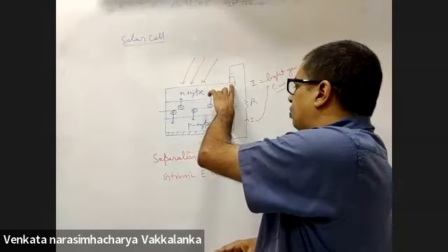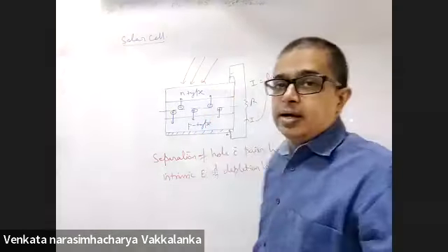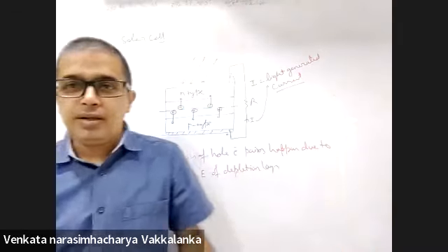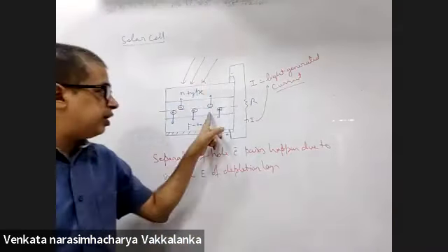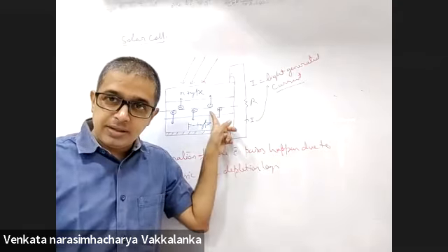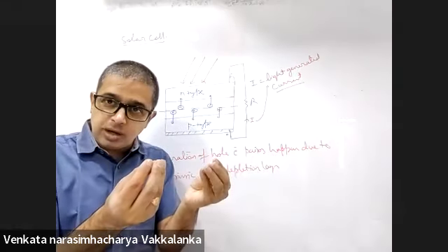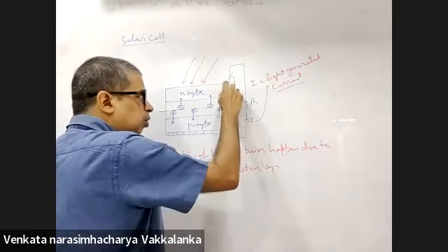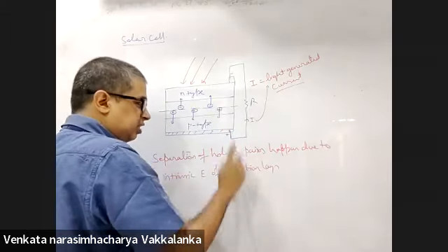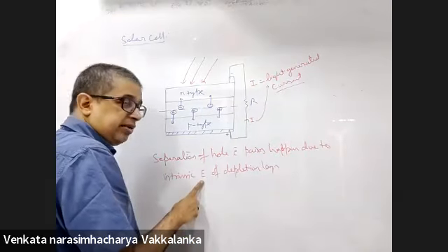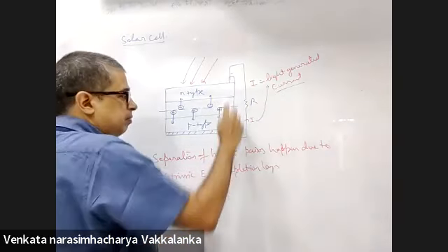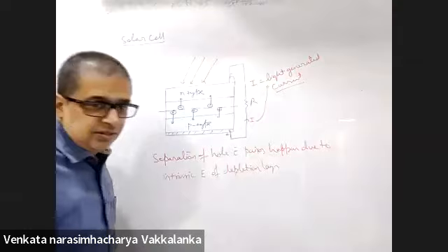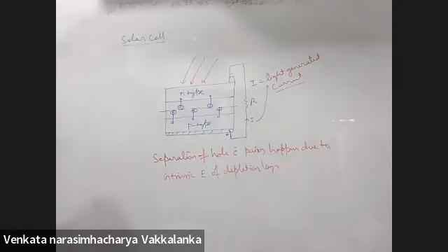That maintains a potential difference, which will maintain current in the circuit. Simple. Light should reach the depletion layer and generate hole electron pairs. These pairs move to the negative and positive sides with the help of the intrinsic electric field. That maintains a potential difference and hence current.